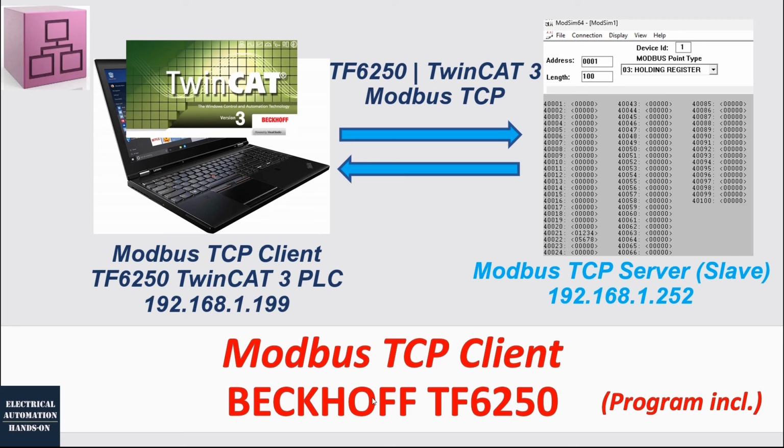The Modbus TCP client function is a very common function when we are doing PLC communication with multiple other devices. For example, some meters and devices can basically all run as the Modbus TCP server side, the slave side. Then when the PLC tries to write parameters or read values from those meters, the PLC will run the Modbus TCP client role.